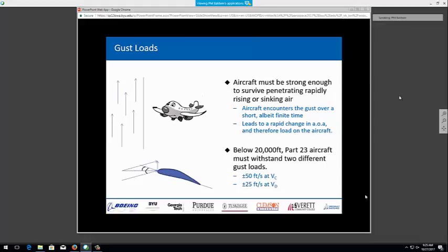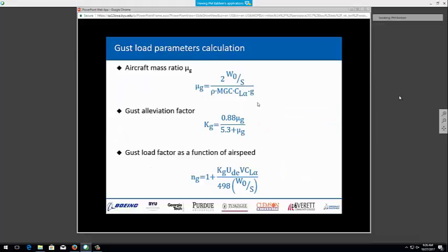This type of method, for instance, for the wing or the beam, as Carl said, gives you the total load. And then you need the load distribution also. But as I said, one of the tests that's very commonly done for model airplanes, a small UAS, is to pick the airplane up by the wingtips. And that comes close to a 2G load for an elliptic wing. But I think you've got a couple of tools that will give you that distribution that you could also put into the finite element analysis. And the integral of that distribution would give you the load that we see on the Venn diagram.